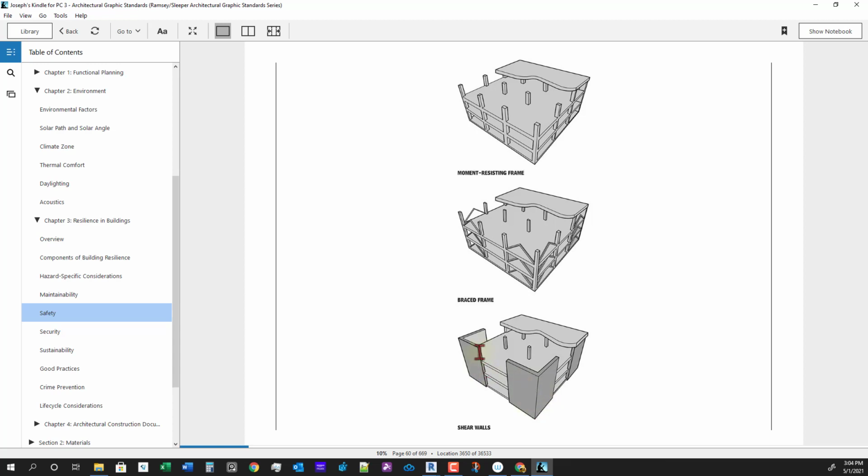So basically, a shear wall is a wall built in such a way that it will actually resist shear. It will either have diagonal X brace frames, or it will have hold downs in the corner, which connect to whatever studs there are to reduce the movement.